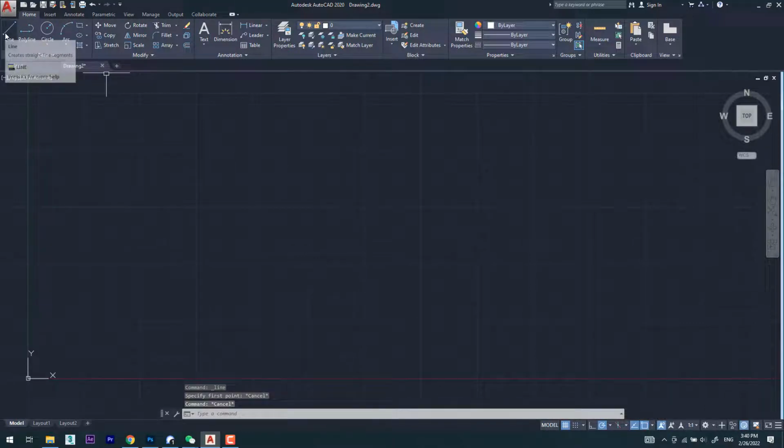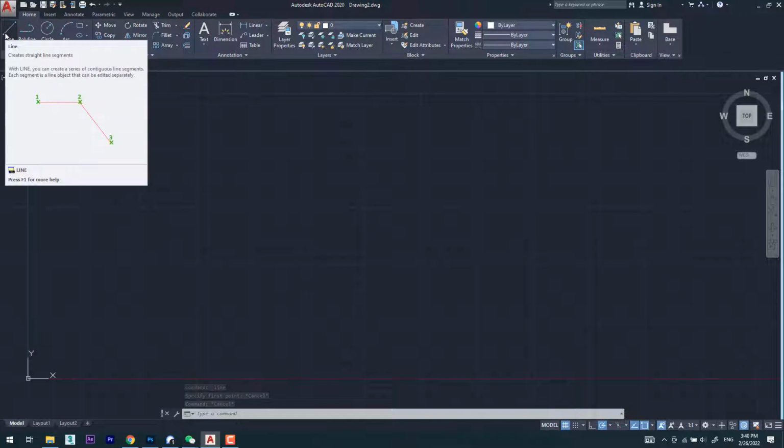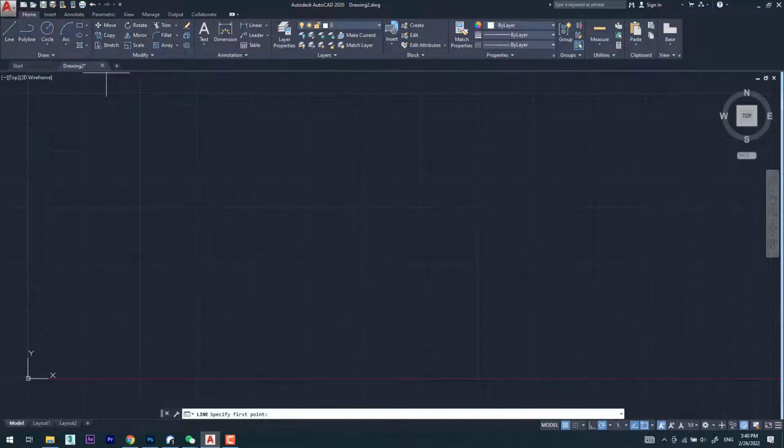Now I want to draw a line, but before drawing the line, I want you guys to understand the units. For example, I give a dimension to the line. Start from here. I want to give 300 or 500 or 200 or 60. What is that 60? Is it inches? Is it feet? Is it centimeters? What is it? So that's what we have to tell the software. Okay, if I write 60, consider that 60 to be inches, feet, centimeters, or millimeters.